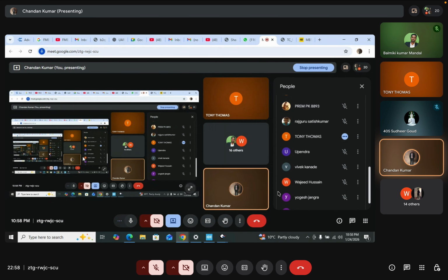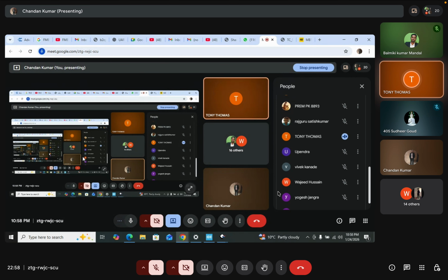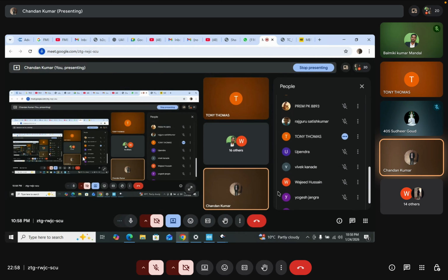Yes, but the controller which you are using has ST-Link also. The point from where you are connecting it using USB will create the ST-Link, and that ST-Link will make one COM port for you. But the PB6 and PB7 UART pins we selected are not connected to this ST-Link, right? No, they are connected. Every UART pin available on this controller will be connected to ST-Link. You can see in the schematic.